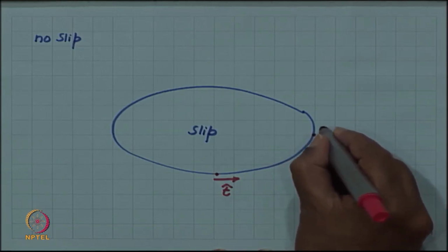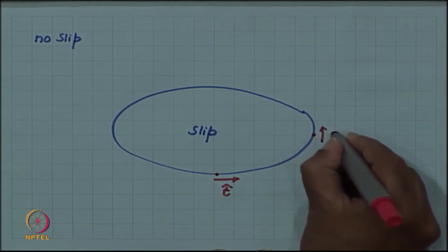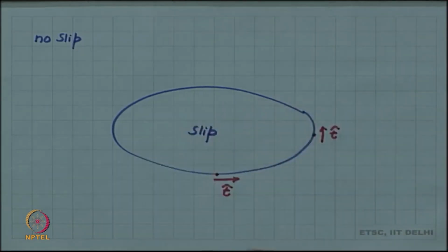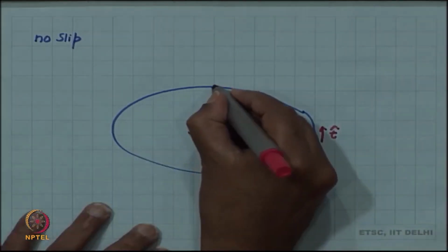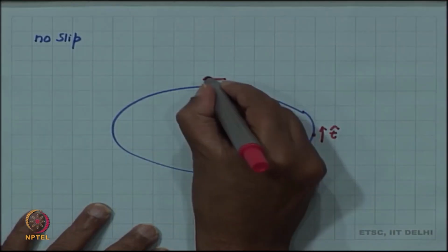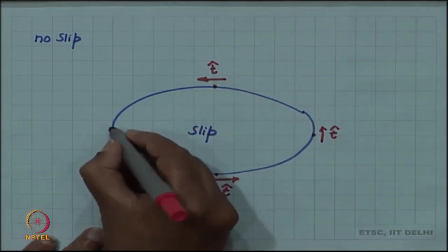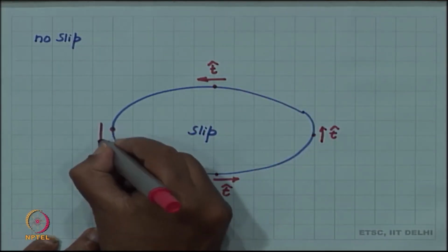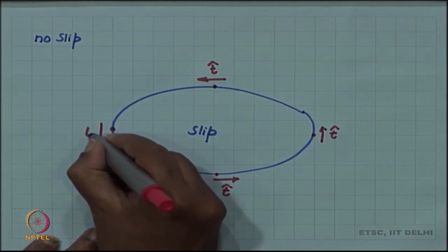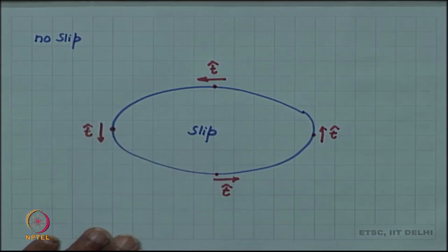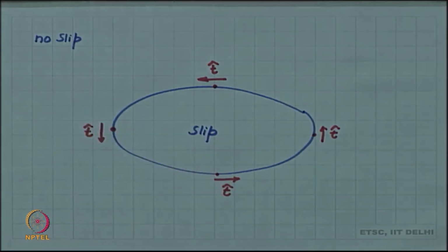On the dislocation line, the tangent vector should appear as if a single current is flowing. So, we keep the sense consistent with that fact. We get a T vector here pointing to the left and a T vector here pointing down. So, the T vector obviously, as we have discussed in the last video also, changes from point to point for a curved dislocation line.